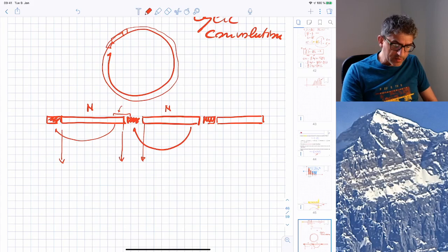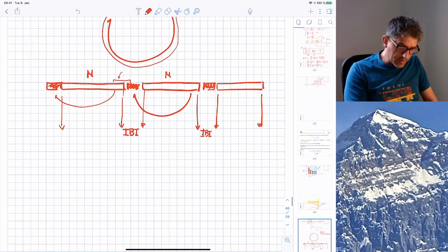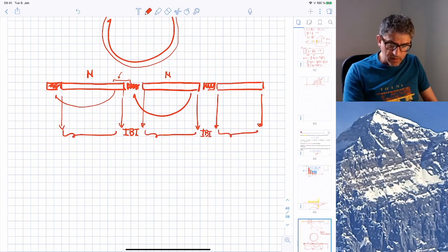So this is called interblock interference, and we just discard this because it mixes the blocks. Then we take, again, these samples here, and then we have a small interval of L interblock interference that we discard, etc., etc. So at the end, we take only these blocks of good outputs that depend only on inputs from the same block.